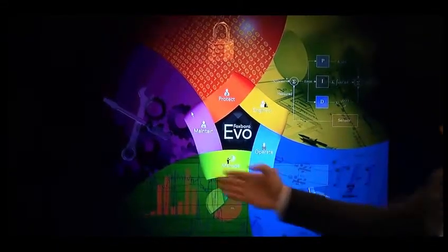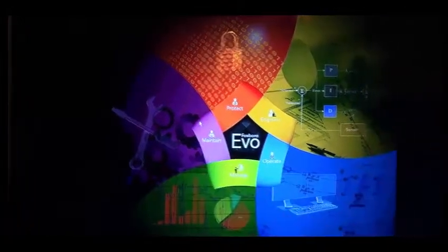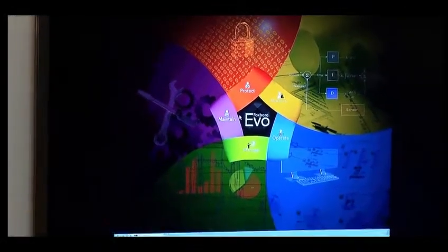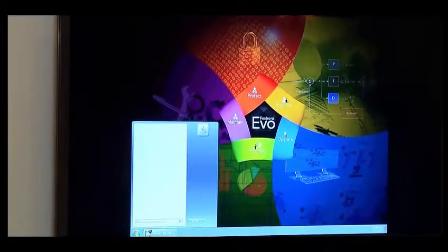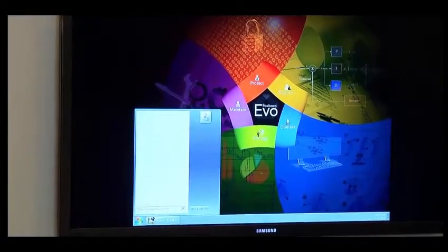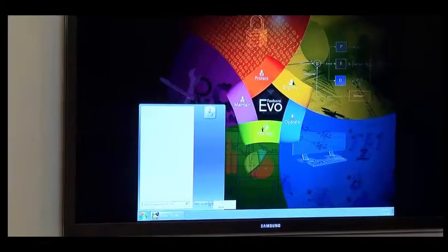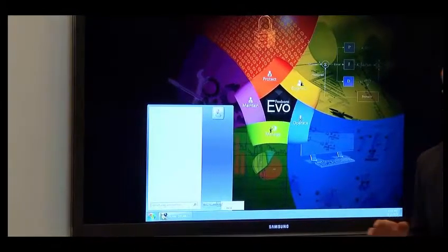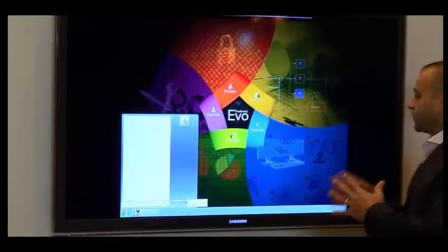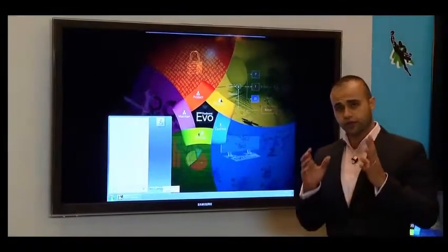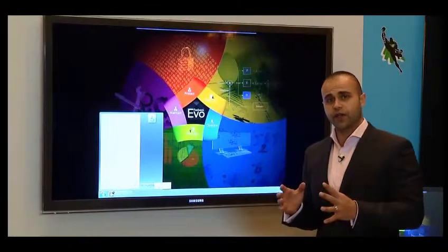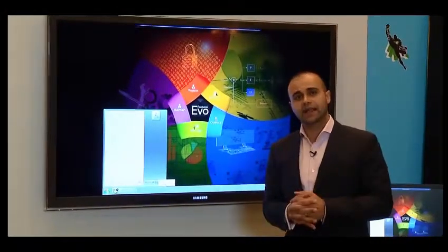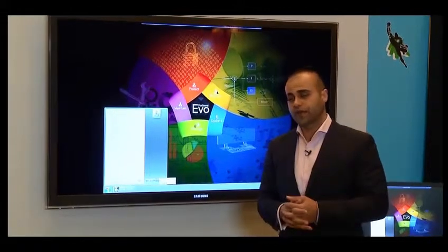The first thing that you'll notice is that all of the icons are gone. Another thing you may notice is when right-clicking, the context menu is completely disabled. Over here on the Start menu, everything is completely blank, and as a matter of fact, I as an operator don't even have the ability to shut down the system. The only thing that I can do is specifically view the Fox View panel, control my plant, do the job that I was hired to do, and not even turn this system off so that we can maintain the highest availability possible for those operators.